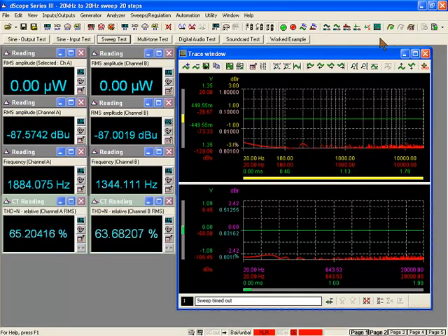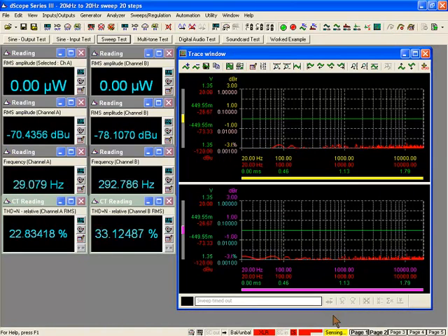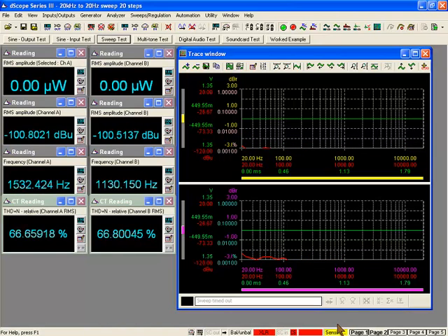Okay, so I'm ready to run the sweep. When I hit the button here, this arms the sweep, which is currently now sensing, it tells me, and it's waiting for the signal to exceed that minus 60 dBu threshold that I dialed in the previous screen. So I will now play my sweep WAV file on my tablet, and we're underway.